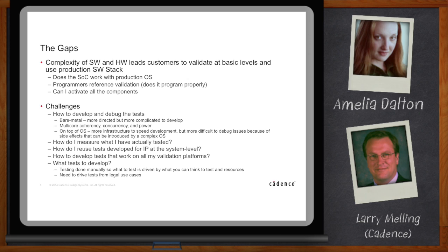I'm not going to get into anything too complex, like what if I have these processors being coherent, and then all of a sudden I want to power down a couple of them. So when they get to those more complex use cases, they say, well, that's going to take too much time to write the test. I'm just going to use my production software stack. I'm going to boot Android, run some stuff on top of it and see what happens.